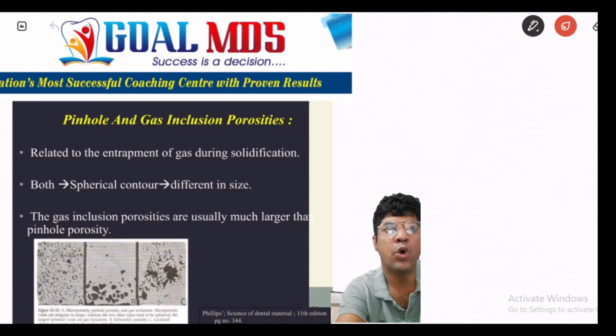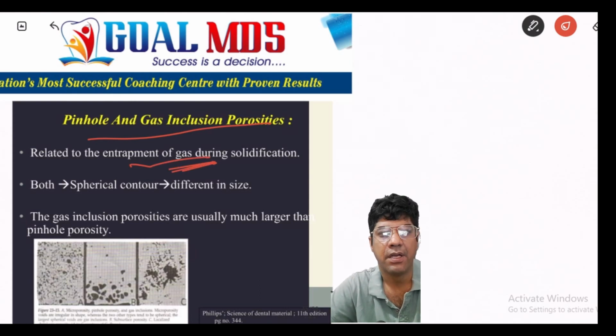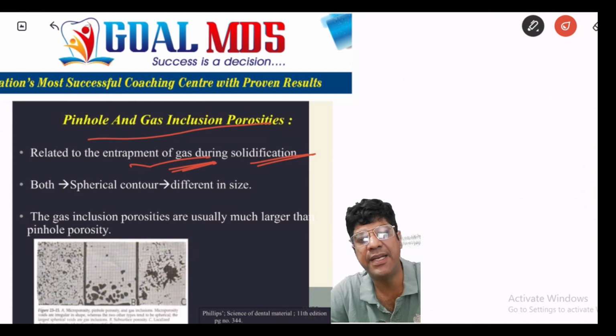Other is the pinhole and gas inclusion porosities. That can be due to entrapment of the gas during solidification. The pinhole porosity is characterized by small size spherical voids in the casting that results from the gas dissolved in the molten metal that is expelled during the solidification.